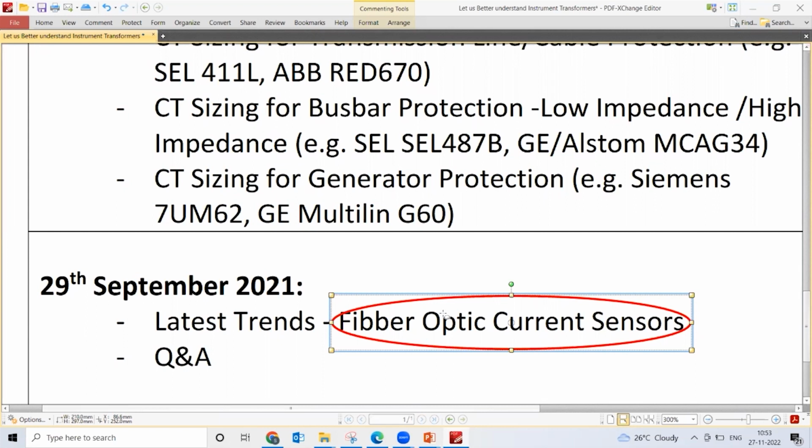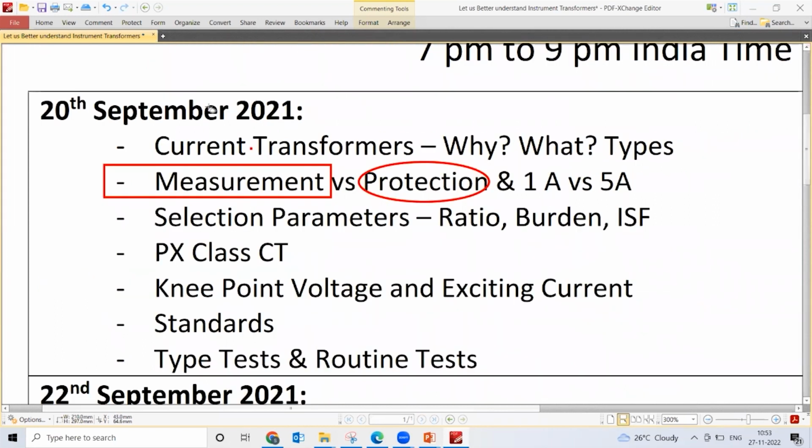And in fact, you cannot use instrument transformers in a DC system, right? Why can you not use instrument transformers in DC systems? No change in flux. Thank you, Sanjay. Yeah. So if you could have used instrument transformers in a DC system, then probably Thomas Alva Edison's DC system would have won the war, not the AC system of Tesla, right?